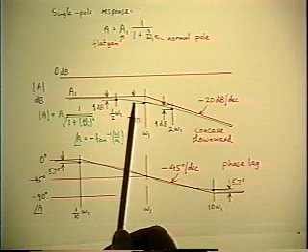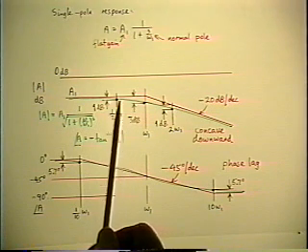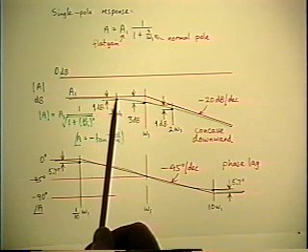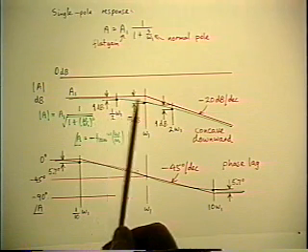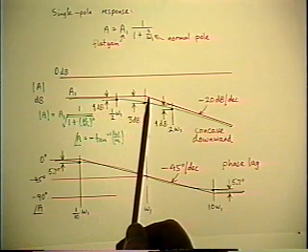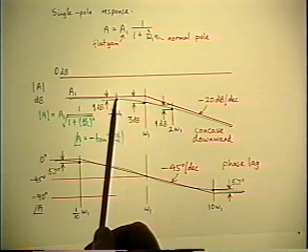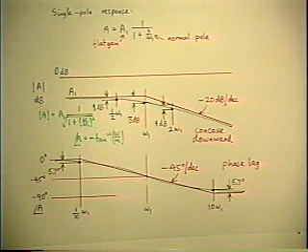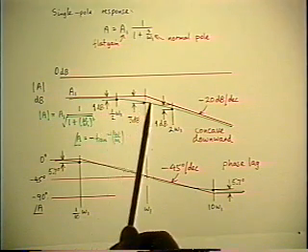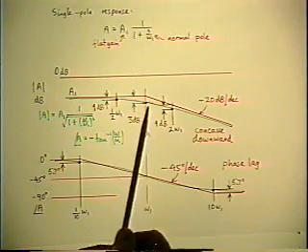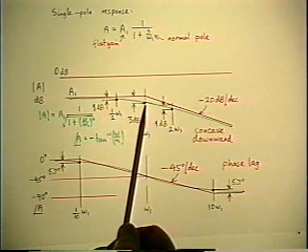And the question you're asking yourself is, the slope's getting bigger. When am I able to say there is a corner up ahead that I can't see in the fog? So the 1 dB down point is that criterion. When the level of the ground has dropped 1 dB, then you can say there is a corner ahead, and it's a factor of 2 away.